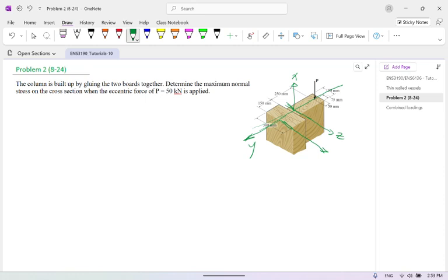So the neutral axis will be found in a different way. But I would say for every part, there's two parts. One is a part of this, one is a part of this. So two parts. That's why we should find the centroid or neutral axis of the parts. So that's quite a simple way for us. If you say, okay, it's 3D, I'm not quite sure, you can draw another way. You can draw like this way. Clear? That's a simple way. So you can see the structures here, you get everything. That's why from here we had so many practices of this thing. It's a simple way. Clear?